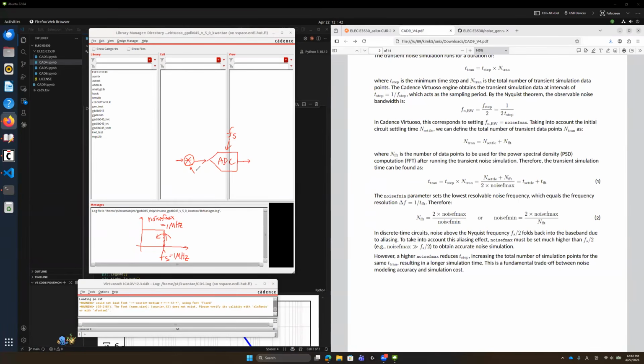Then, if this noise is band limited, it appears like it is applied with an anti-aliasing filter already. So, to accurately measure what is impacting the ADC, to accurately model our circuit analysis situation, it is better to set noise Fmax for running transient noise simulation way higher than the sampling frequency or Nyquist frequency. But in this case, if we increase noise Fmax, then we have to run a lot of transient noise steps, which can make your simulation time slower and slower and slower.